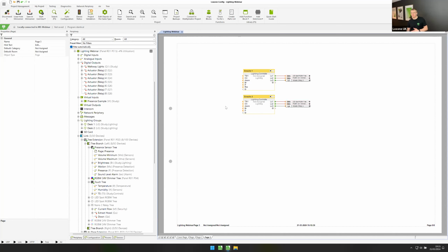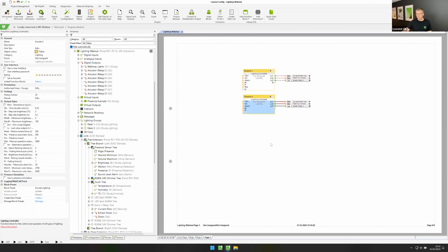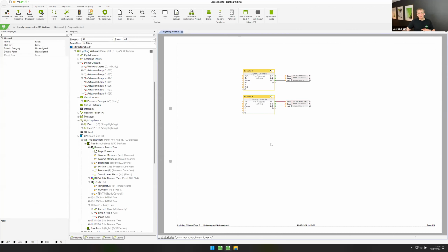Usually when we leave the bathroom, the lights turn off after perhaps 5-10 minutes, 5 minutes in our case that we've set here. But let's say that during the night, once you've left the bathroom again, rather than turning off after 5-10 minutes, we wanted to turn off after 60 seconds or 2 minutes. So we want to adjust that time.